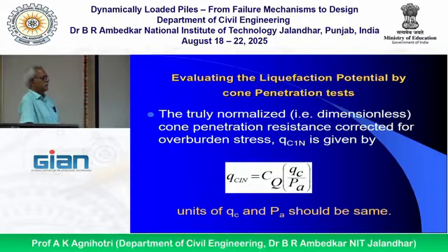So first we will use this QC. So the QC value we have calculated. Let us say our load will be transferred up to 10 meters. So we will start the test from the ground level, say. So the values along the pile length will be used for skin friction load.